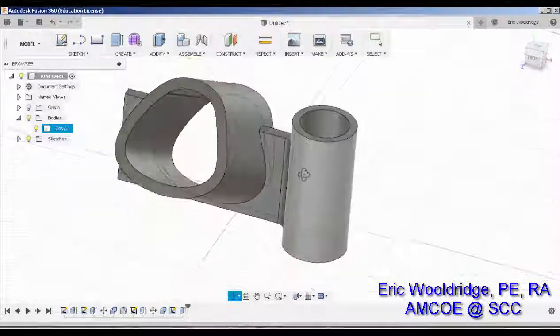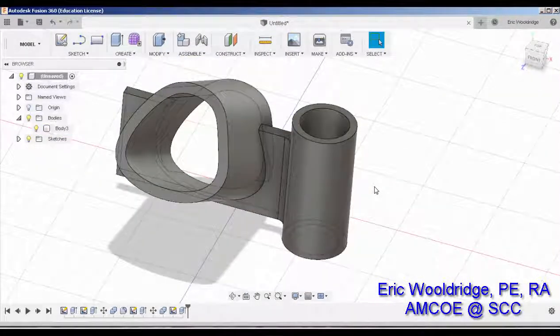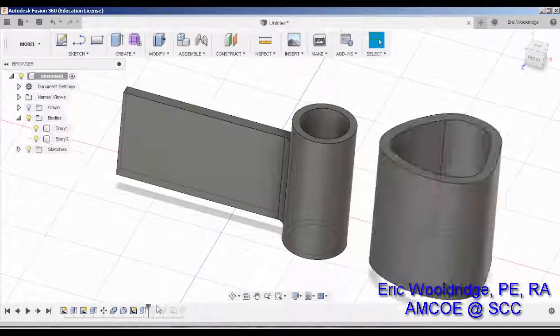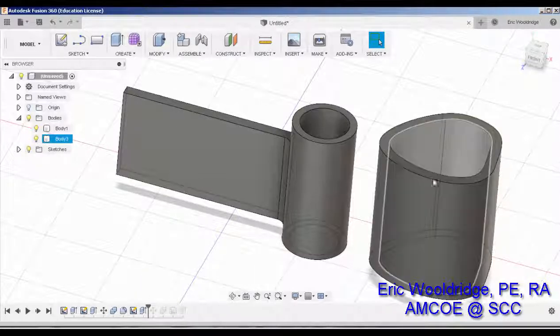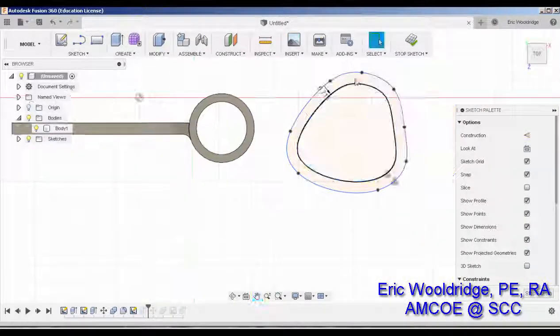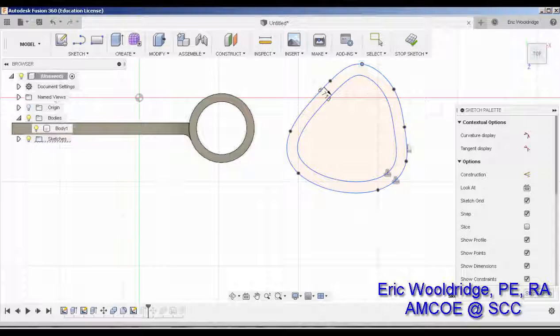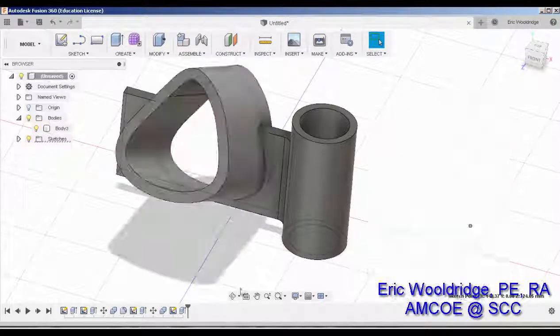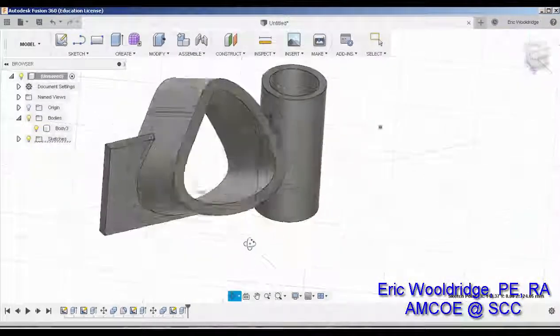There we go. And here's one of the great things about the move. It's created like this, but when I actually go back in my timeline, I can go back to when it was here, and I could change my shape here in its sketch. And let's just say that I do maybe just a little bit of that. Maybe just pull it up just a hair and say stop sketch. And then when I slide my slider back out, everything's updated over here.